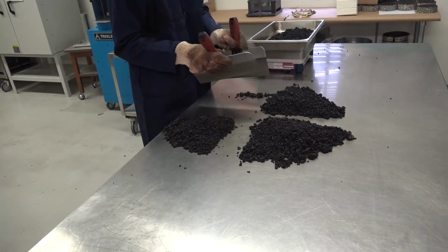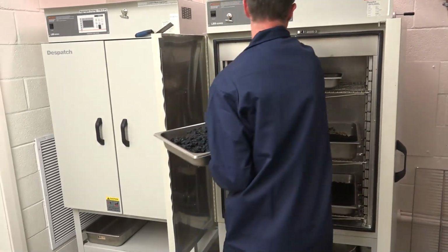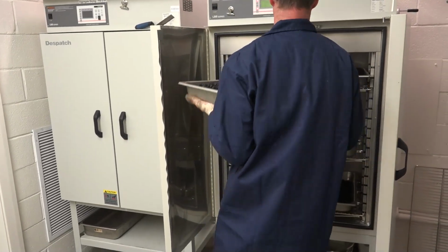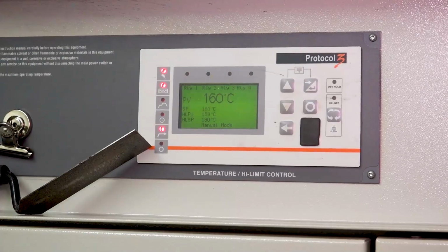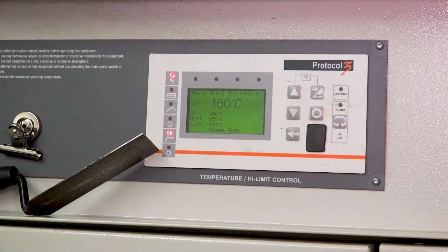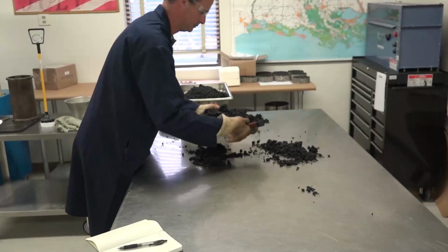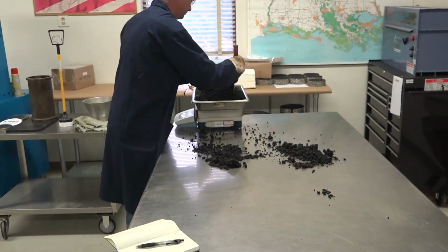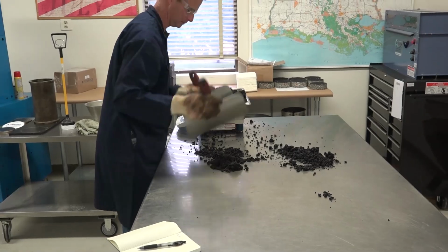Application of Quality Assurance Specifications for Asphalt Concrete Mixtures states that unless procedures require otherwise, the laboratory-produced mix shall be cured for 2 hours and plant-produced mix shall be cured for 1 hour at the compaction temperature plus or minus 10 degrees Fahrenheit. When the aggregate water absorption is greater than 2%, the oven age time for plant-produced mix shall be 2 hours.